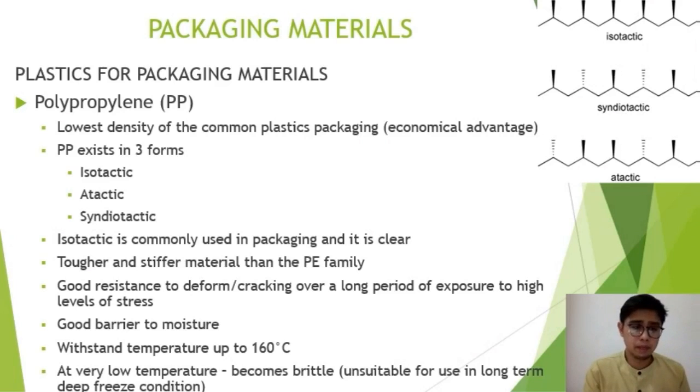The PP plastic also has tougher and stiffer properties than the PE family, and it also provides a good resistance to deformation or cracking over a long period of exposure to high levels of stress. It also provides a good barrier to moisture and can withstand a temperature of up to 160 degrees Celsius, higher than the PE family can withstand. But at a very low temperature, it will become brittle, so it is not suitable for use in a long-term deep freeze condition.